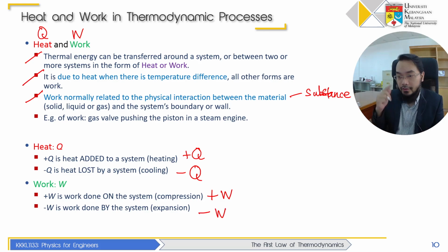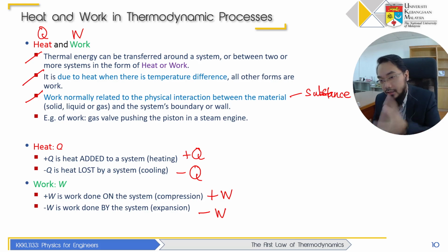So it's very important that you grasp the idea and identify when Q and W are positive or negative. Very, very important. Okay, so let me repeat myself. If heat is added into the system, Q is positive. If the system loses energy due to heat transfer, that means Q is negative.